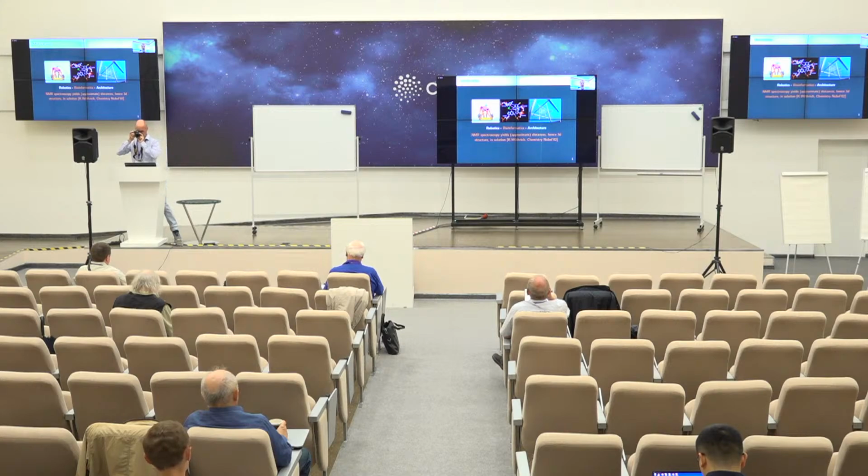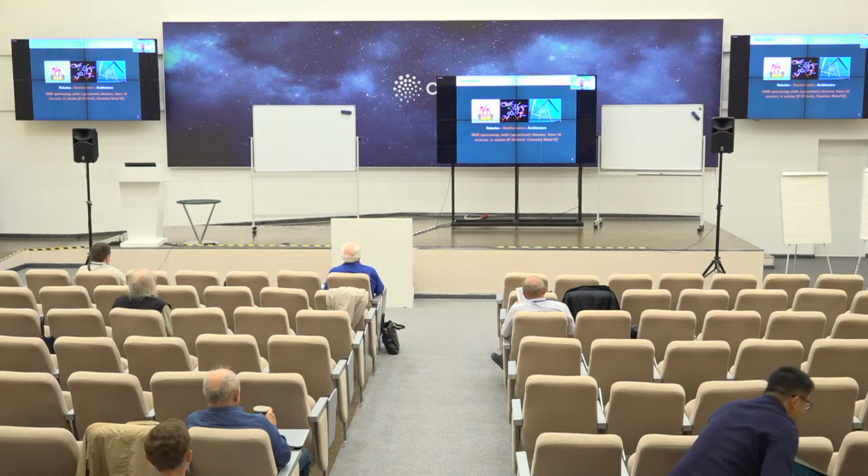The first example comes from robotics, the famous Stewart platform. Some people call it the Gough platform. You have two rigid bodies connected by 6 legs. The only control we have is on the length of the legs. By specifying the length of the 6 legs, we control the position and the orientation of the end effector. Because we are in free space, there are 6 degrees of freedom for the position and orientation of the end effector, so we need 6 controls. The connections are free to move and to rotate, but we can control the length of the 6 legs.